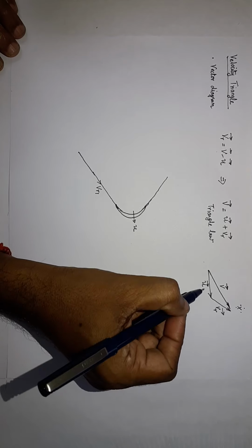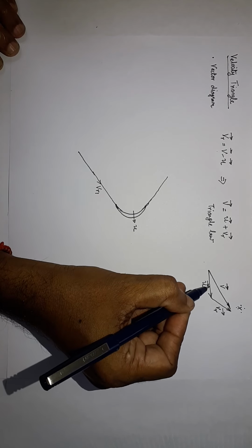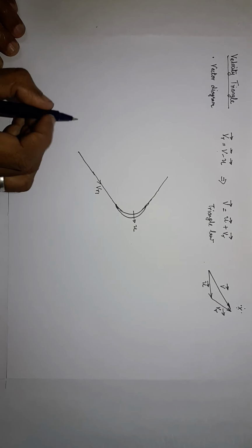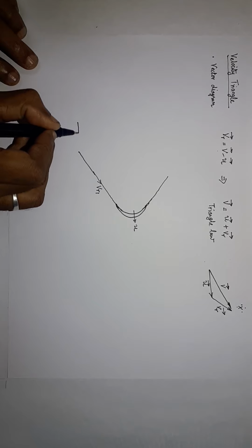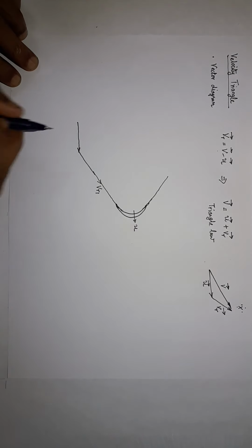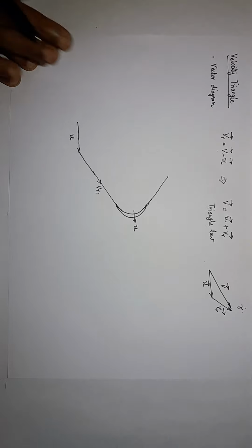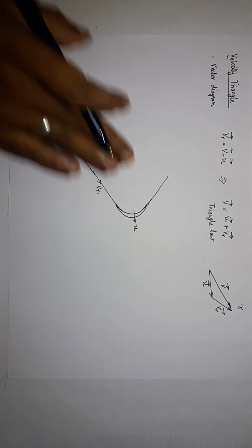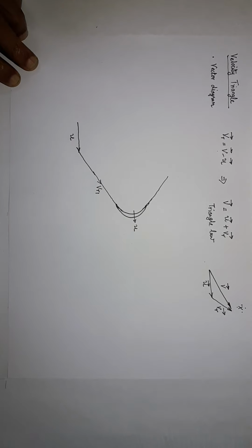Okay, you see here, the relative velocity vector should be added with the blade velocity. So this is the blade direction, and I should draw the same thing here. So it is reality, we are drawing the actual system. This is the direction in which the blade is moving, so I should not put it in the opposite direction. The liquid is coming, the vane is moving in this direction, so the same direction I have to follow here also.